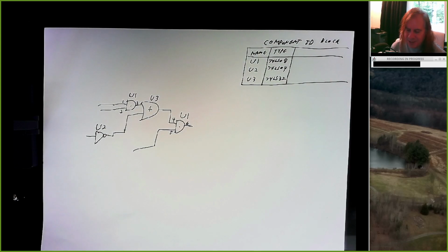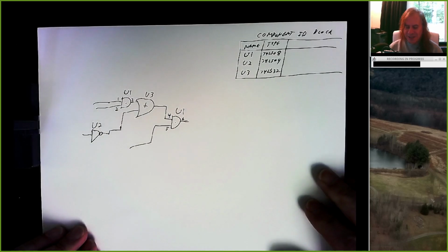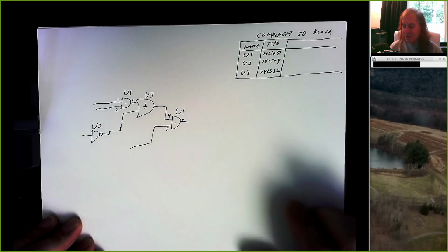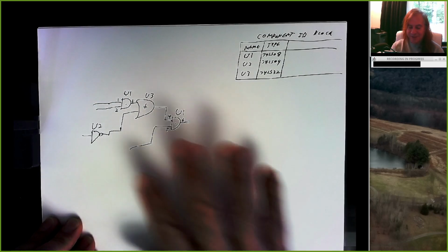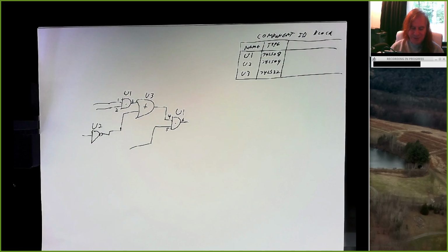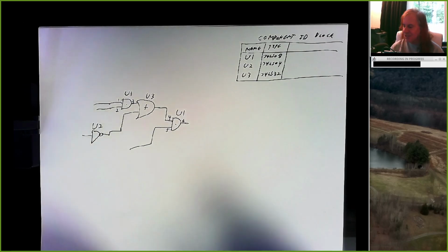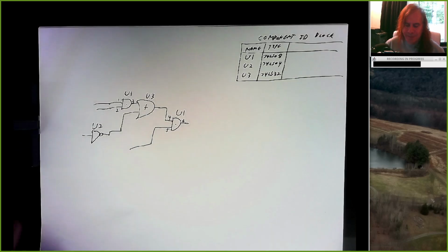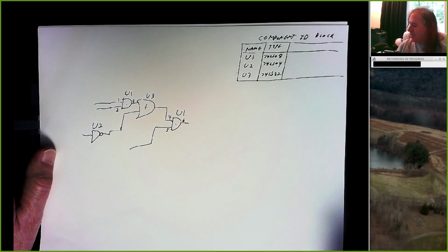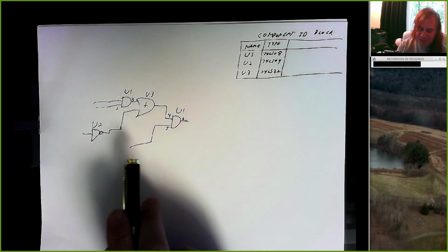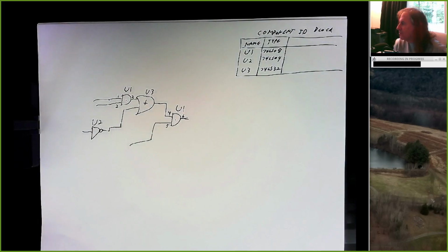And if you were in the lab and you built your circuit and it didn't work, and you went to a lab assistant for help, first thing they're going to say is, let me see your schematic diagram. And if it doesn't have part numbers and pin numbers and a component ID block, they're not going to be able to help you. And if you don't have this information on your schematic and you're trying to debug your circuit, you're working in the dark, right? You're fighting the logic, the wiring, the implementation, the possibility of faulty circuits or a faulty protoboard, and you have no idea which of those you're going after. So this is super important. And it's worth a ton of points on the grading of Lab 2, that you have a good schematic diagram with component IDs, pin numbers, component ID block.